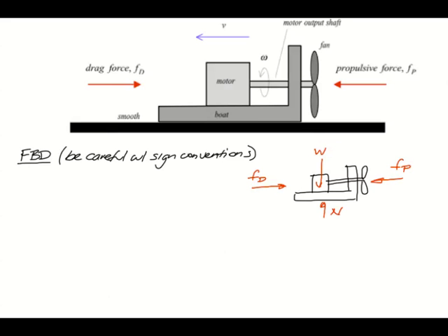The picture here suggests that we should use a sign convention for omega, which looks like this. Well, if you go back and look at the notes that we use to derive the motor equations, the sign convention in the load torque is just the opposite of the sign convention on omega. That was our choice then, and we'll stick with that here so that we can use our motor equations as they are. So again, have T sub L with the opposite sign of that shown for omega.